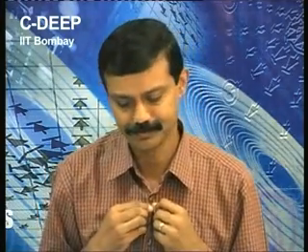You can divide T1 depending upon what sort of harmonic spectrum you want, because a large number of different PWM techniques have been proposed by dividing this T1 period into a large number of different parts. Similarly is true for the V2 vector. So more about it I will explain in the next class. Thank you.